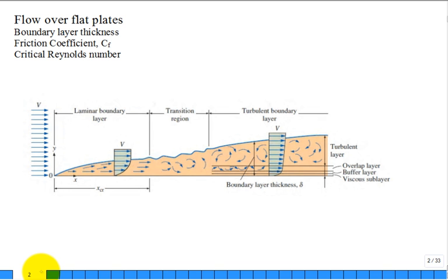So what do we start out with? We start out with a very sharp knife-edge flat plate and a uniform flow field approaching the stationary flat plate. And the flat plate's aligned with the flow, perfectly aligned, no angle, perfectly aligned with the direction of the flow. Well, this flat plate is not moving. When the fluid comes into contact with it, there's a no-slip boundary condition. Hence, the fluid somehow abruptly comes to zero speed at the tip of that flat plate.